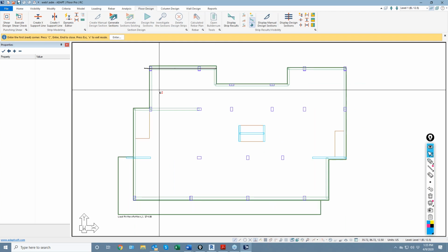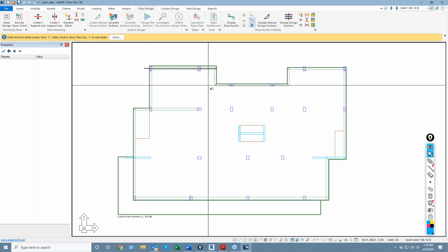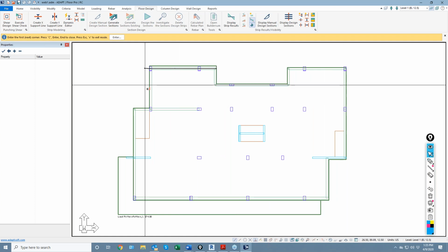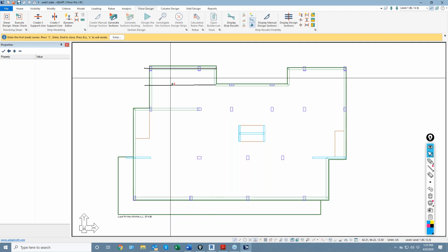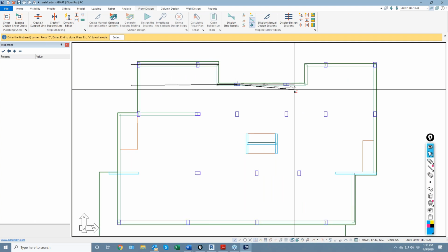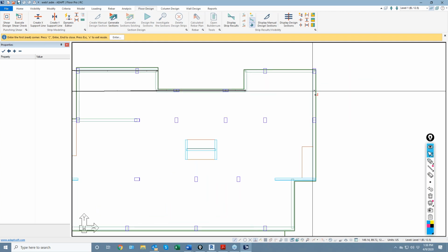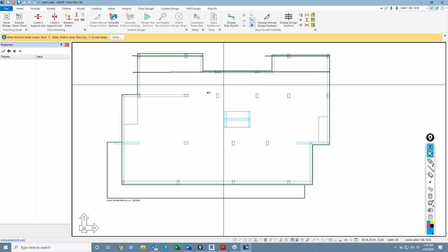Okay, and we'll do something similar. I'm going to assume that this is a middle strip that flows into a beam and then flows out back into a middle strip. So we'll go ahead and I'll snap there, I'll enter. That's going to be designated as a two-way slab. This will be designated as a beam. And then we have, again, a two-way slab. Okay, on this side, this will be purely a beam strip here.